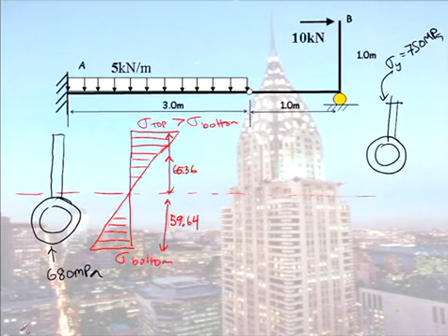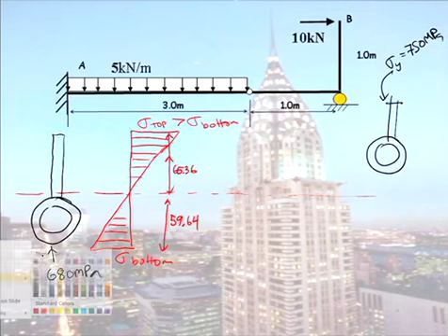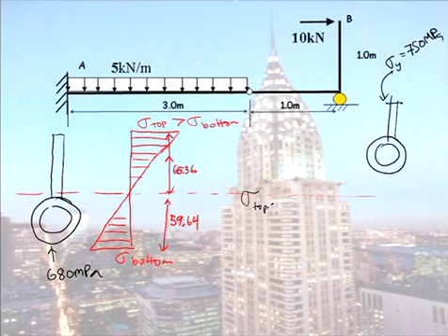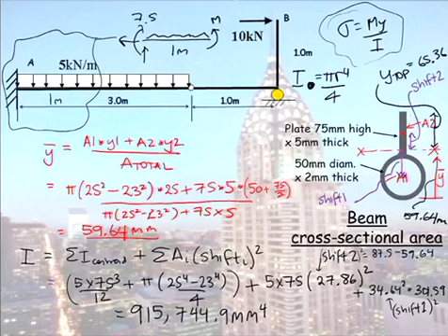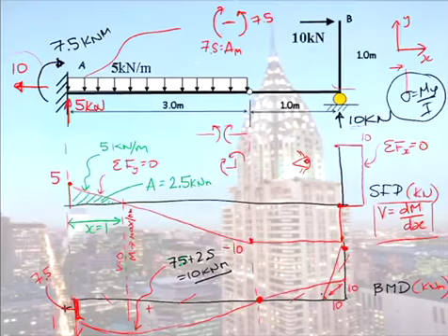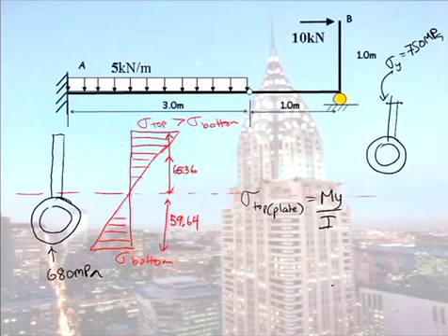So let's calculate some stress values now. So the stress at the top in the plate is My on I, because if you go back to our bending moment diagram, it had the same maximum value of 10 and 10. We only need to check it at one location.